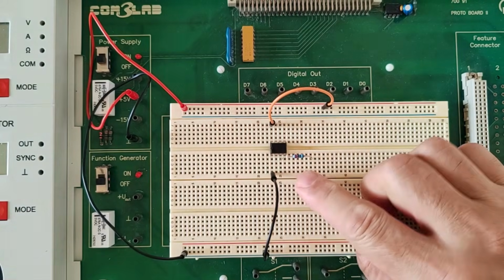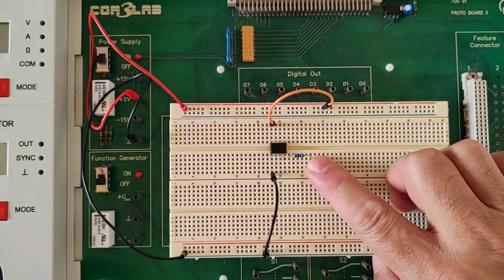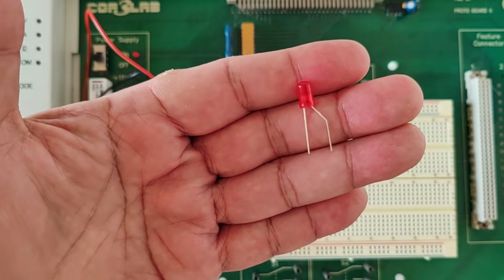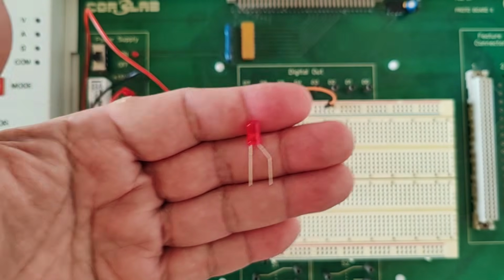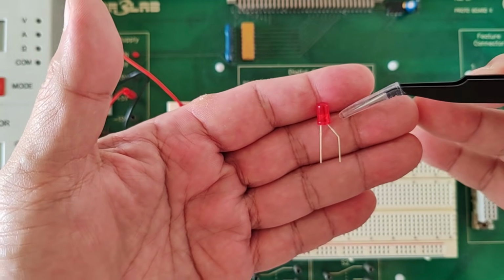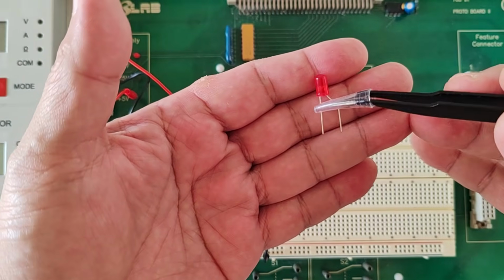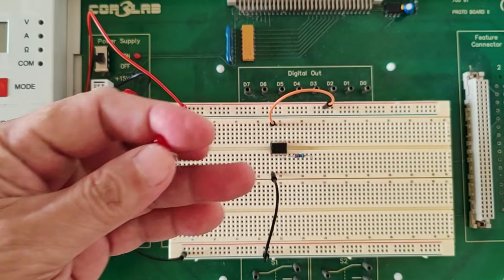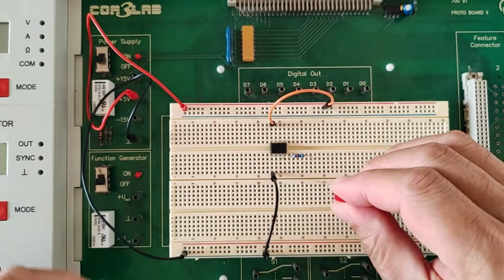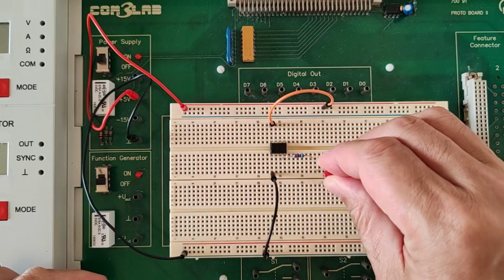The other leg, one leg to pin 3, the other leg to a free pin somewhere on the right. And that other leg connected on the free pin will have to be connected to an LED. Which side of the LED? You have to connect it on the anode side, the longer leg. The cathode will be grounded based on the schematic. So let me connect now the anode to the other leg of the resistor, like so.